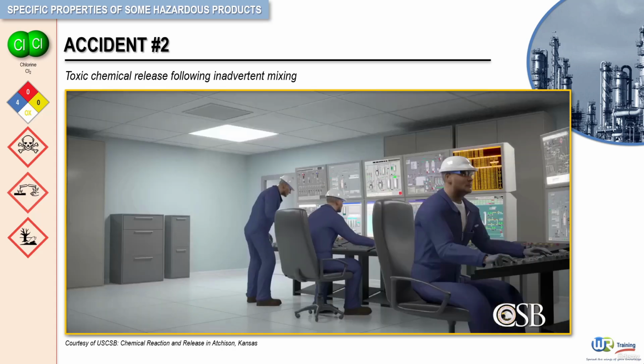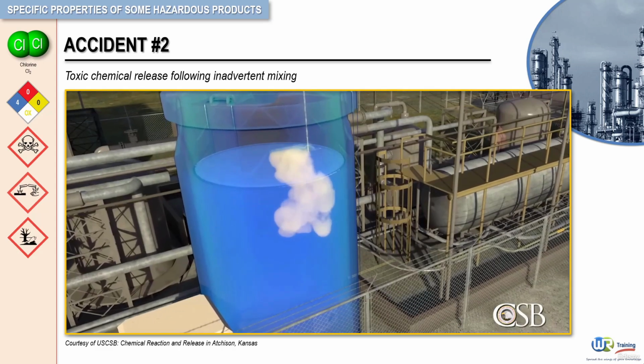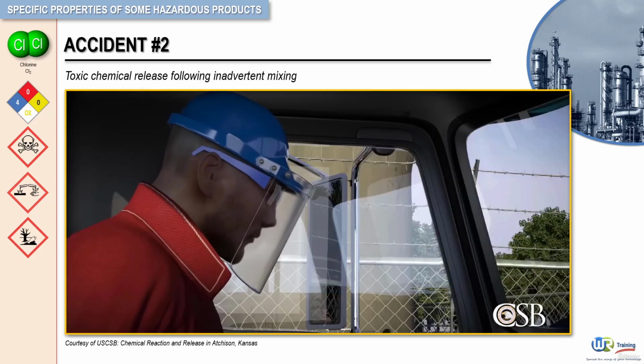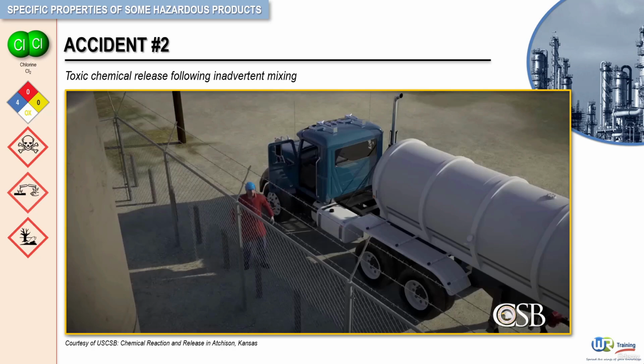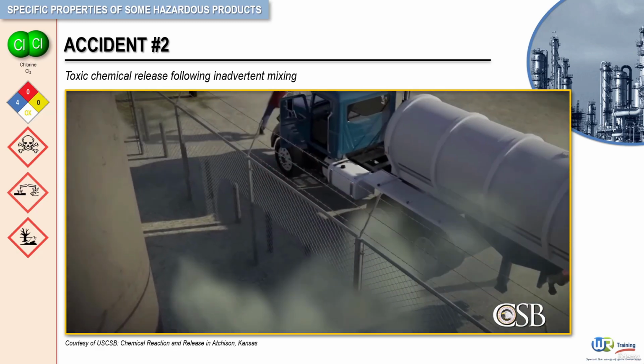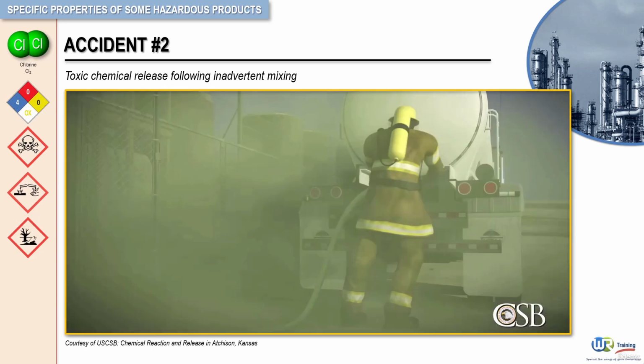Also during its investigation, the CSB found that at the time of the incident, MGPI did not have instrumentation that could automatically shut down the transfer of chemicals from the unloading area in the event of a process deviation, since the only ways to shut down the transfer of sulfuric acid to the sodium hypochlorite tank required human interaction and were located within areas affected by the release. There was no way for workers without proper personal protective gear to stop the flow once it began.